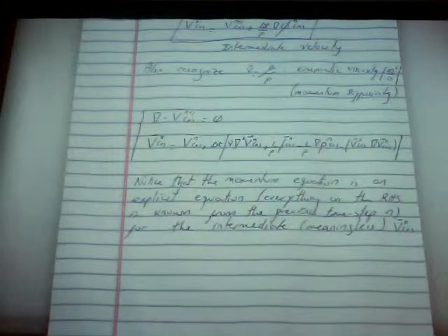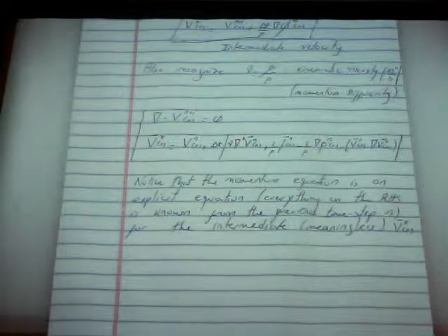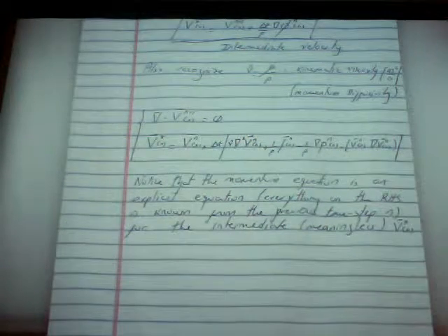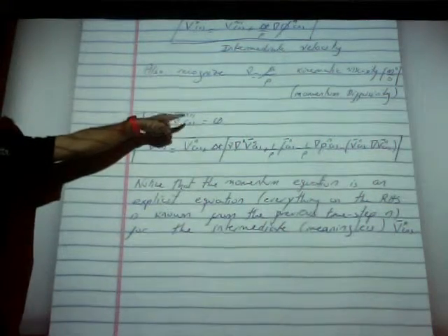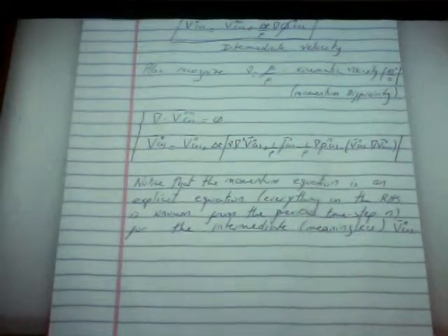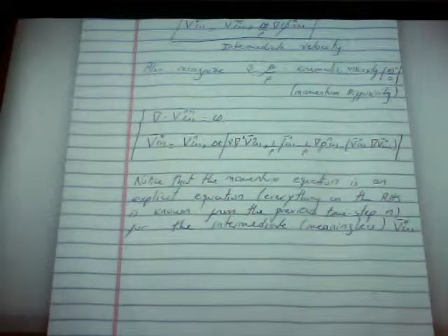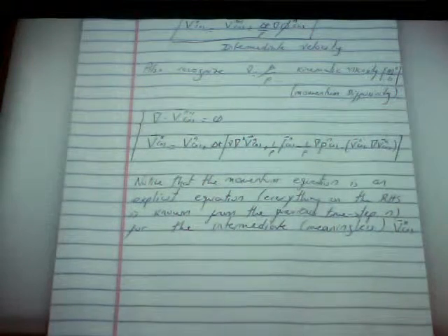So now what do we do? We got a transport equation that is explicit. We got a useless velocity, V star, and somehow we got to make sense of these and be able to use that to find V at n+1 and to find the pressure at the next time step. Okay, so far we haven't done anything. What we have done is just rearrange the equations to make it look pretty, but useless.